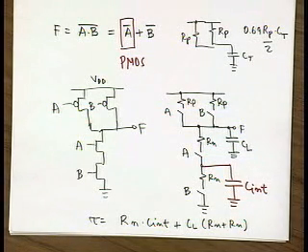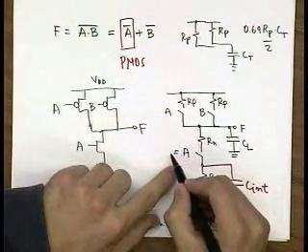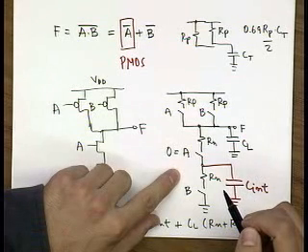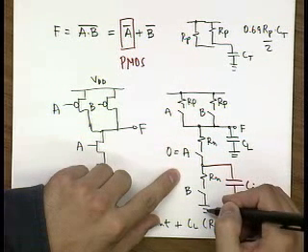Questions? Suppose my A input is 0, and then my PMOS transistor is on and it's pulling up. So how is that internal capacitance C getting charged? So let's say your A input is 0. Okay. And then how is C internal getting charged? By discharging, it will discharge through that bottom Rn. Right. How is this getting charged?